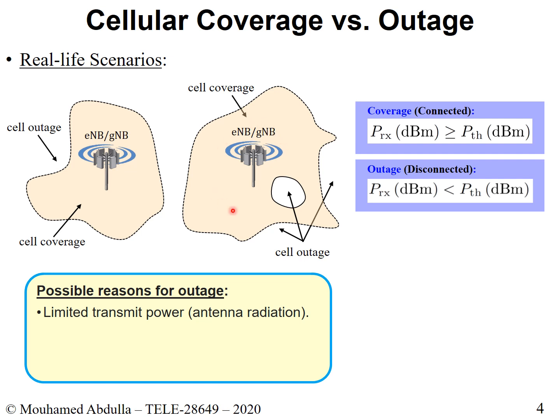The cell size of your antenna is smaller. Not all antennas have the same coverage. Maybe I mentioned it in the previous lecture, not all cells have the same coverage. You have some cells that will give you large coverage, in the kilometers, up to 1 kilometer. And then you have smaller cells that will give you less than perhaps 500 meters. So it depends on the type of coverage.